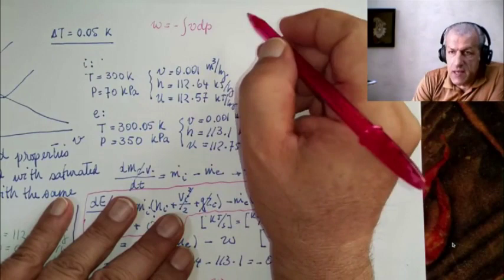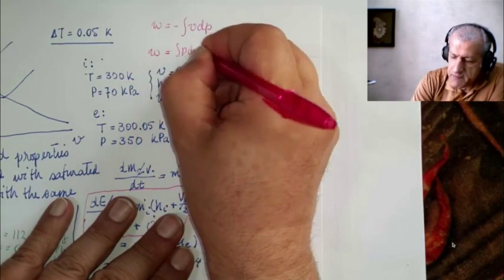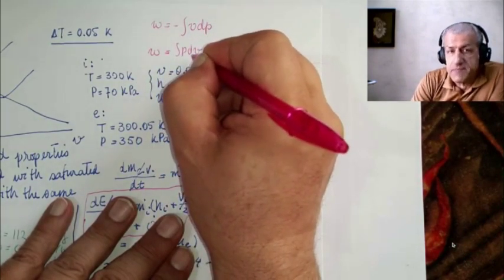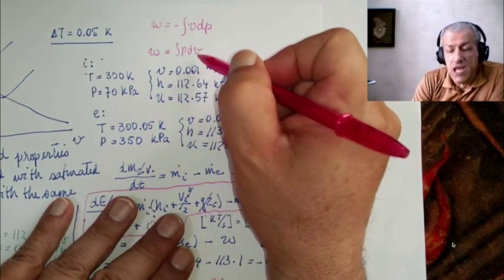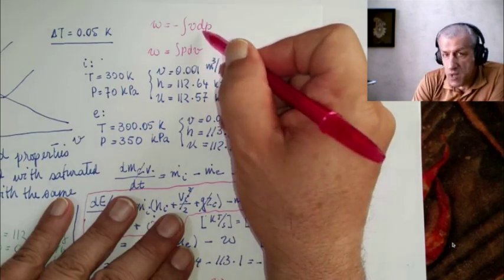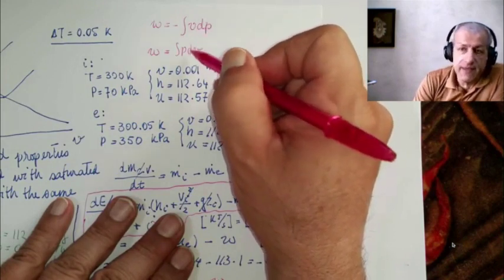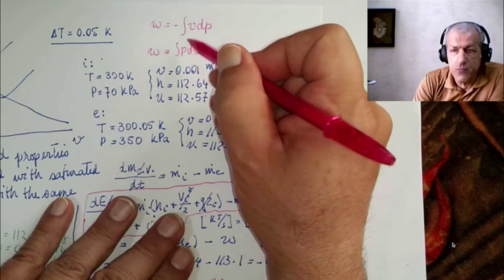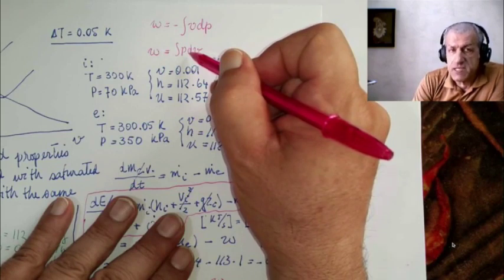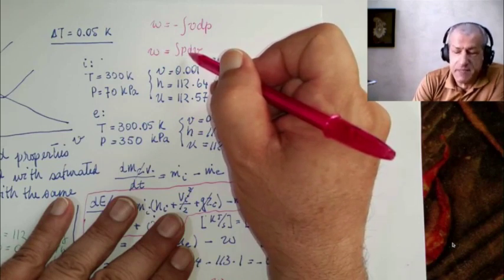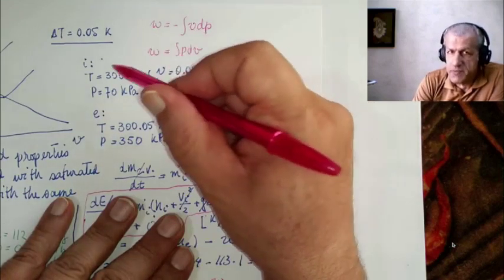This equation, you see, when we had another equation, W equals integral PdV, which was only valid for a cylinder piston arrangement. This equation was only valid for a changing boundary. For a control volume, both are for reversible or semi-equilibrium processes. Both are for them, but this is for a system, for a changing volume system, often used for a piston cylinder arrangement. This one is for a control volume, just like the pump that we used.